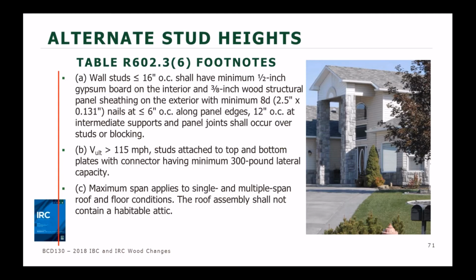The second footnote deals with when you have wind speeds that are higher than that 115, which is the center of the country area. And when winds are higher than that, you're going to actually have a connector that's attaching the studs up to the top plate and down to the bottom plate with a minimum 300-pound lateral capacity, which is new, something we haven't had a requirement for, and is occurring because we have these taller studs.